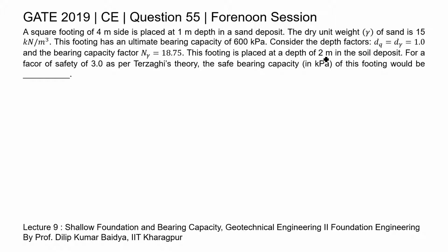This footing is placed at a depth of 2 meter in the soil deposit. For a factor of safety of 3 as per Terzaghi theory, the safe bearing capacity of this footing would be. So this problem is from the topic of Terzaghi bearing capacity theory. You may watch lecture 9 Shallow Foundation and Bearing Capacity, Geotechnical Engineering 2 Foundation Engineering by Professor Dilip Kumar Vaid, IIT Kharagpur for detailed knowledge and derivation of the Terzaghi bearing capacity theory.